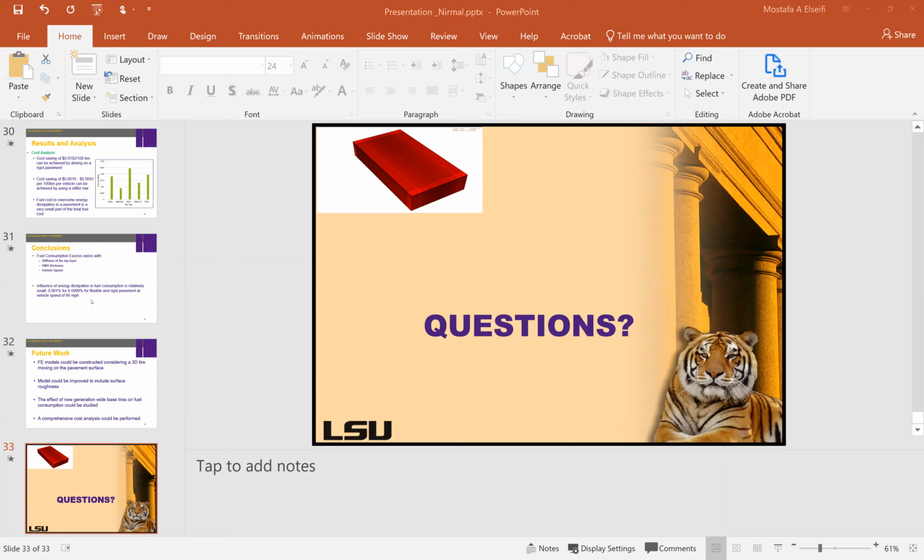Thank you for your nice presentation. I think your approach is more sound than what MIT has done. MIT looked at the deflection under a flexible and a rigid pavement, and that small difference in deflection they used to estimate the fuel consumption due to rolling resistance. An important highlight of your work is that this difference between the two pavements is very, very small.